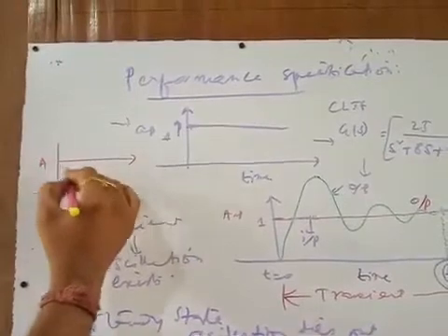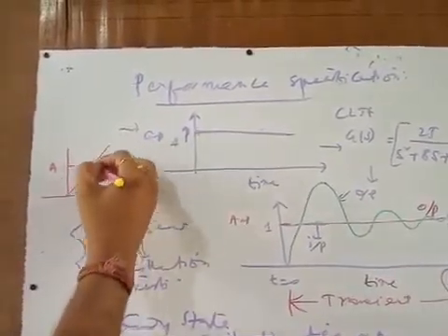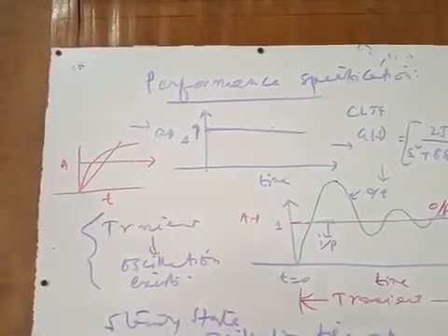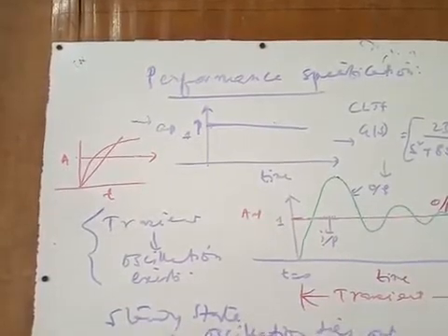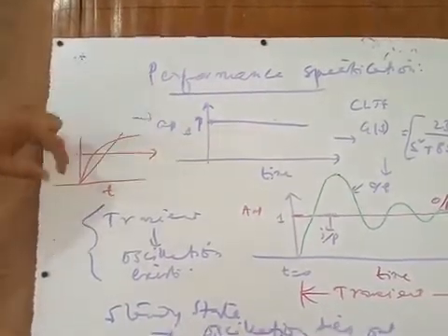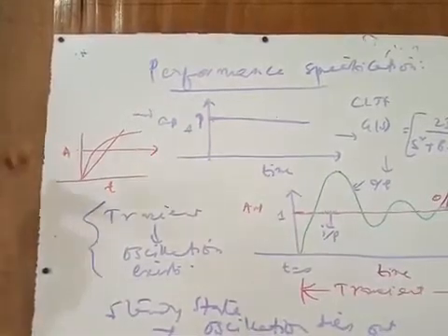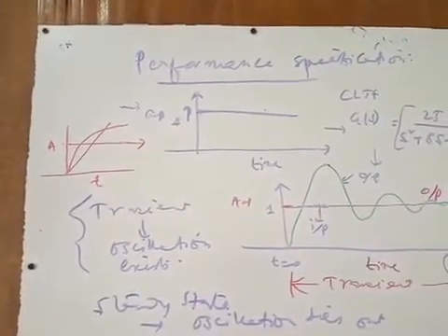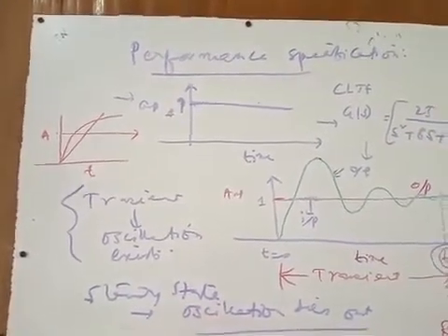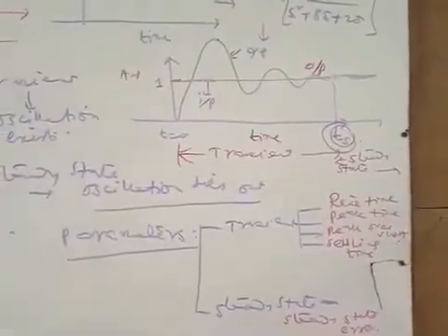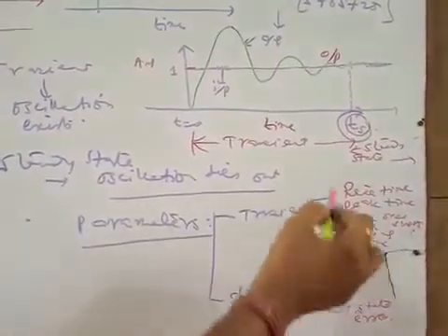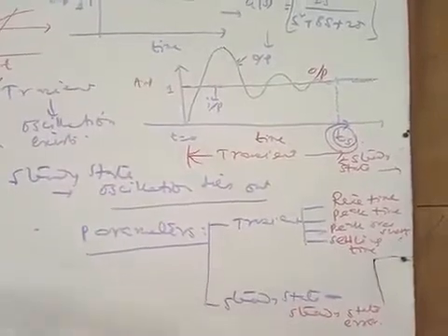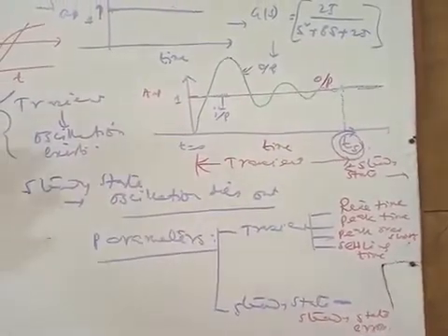In the case of a ramp, you have to follow this type of curve. In the case of a parabolic signal, you have to follow this kind of curve. Getting the error signal for ramp and parabolic signals is very difficult, and we will discuss it later. So the step signal is used as the input for any kind of signal testing, and we get the defined parameters corresponding to transient and steady state. Now how can you understand these parameters, and what parameters can you get from the output response? I will discuss that in detail when I show the mathematical formulation.